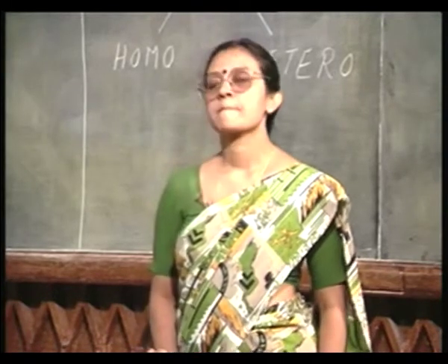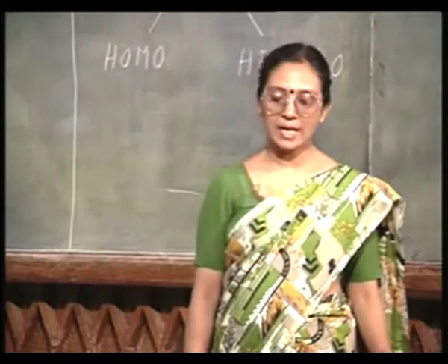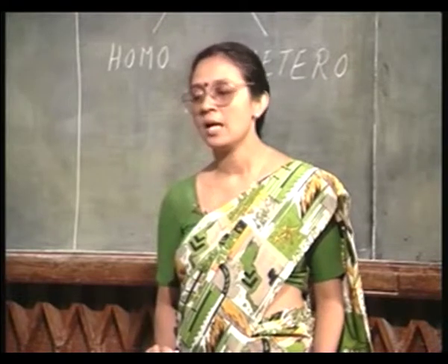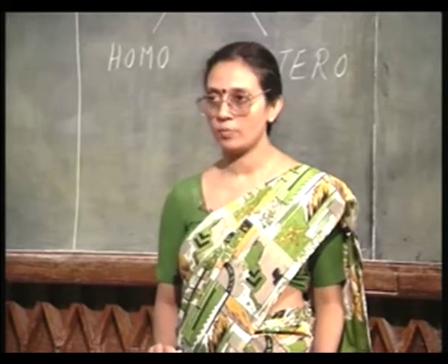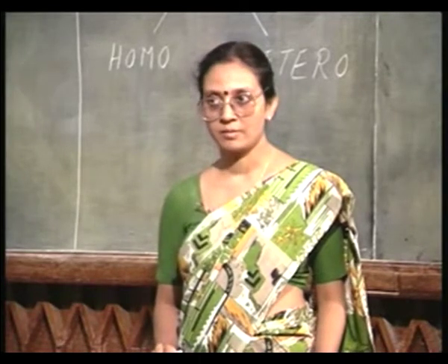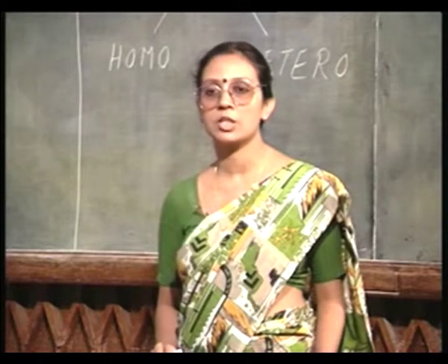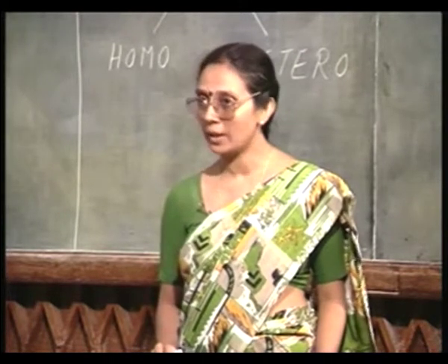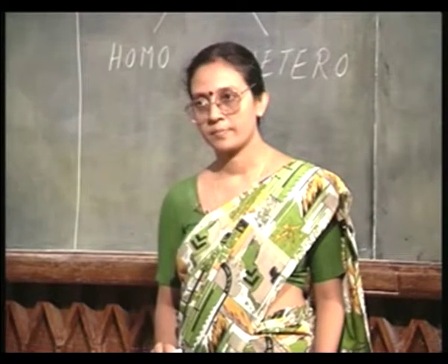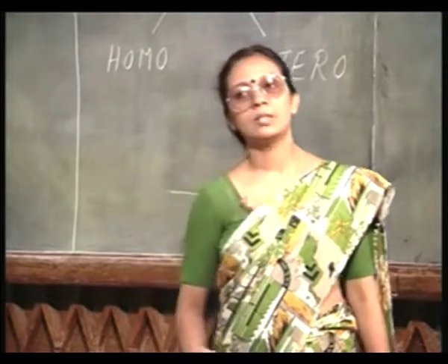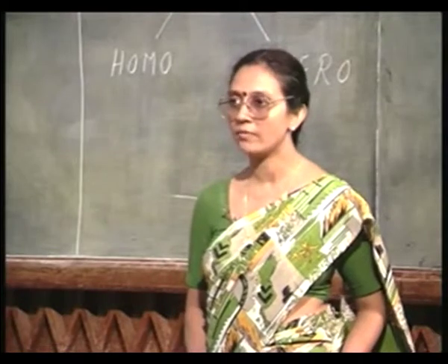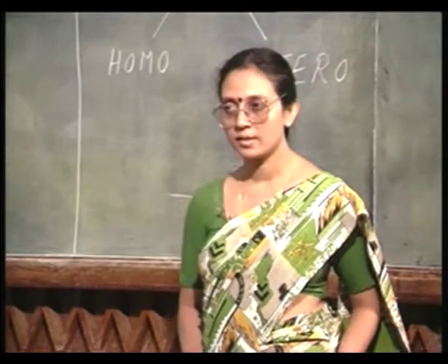In contrast, if I have a certain crystal as the substrate, as the bulk material, and I want to grow something else on top of that. That is, if I have two dissimilar materials, the material of the epitaxial layer is dissimilar from the bulk material, then it will fall under heteroepitaxy. A very common example of heteroepitaxy is silicon on sapphire. You might have heard of it, SOS, silicon on sapphire.